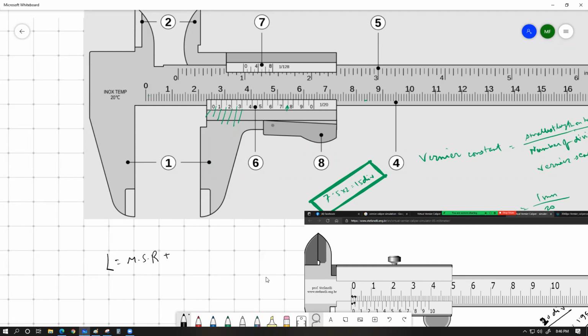Special scale in this case is the Vernier scale. For the micrometer screw gauge it is going to be the circular scale. That value is measured by Vernier scale division number multiplied by Vernier constant. You have to understand this is just a number of divisions.